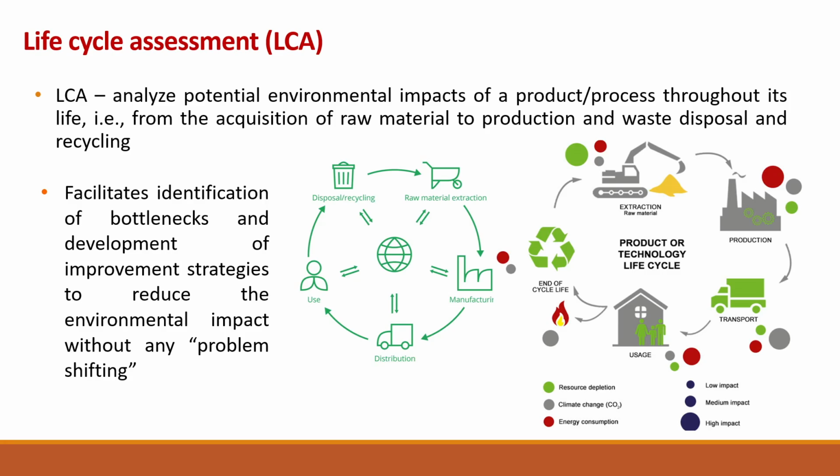So what do we basically do with LCA? As the name suggests, it's life cycle assessment. You have to analyze the impacts of a product or process throughout its life. Throughout its life means from acquisition of raw material. How you are acquiring the raw material, and what impact that acquisition method will have on the environment, you have to consider.